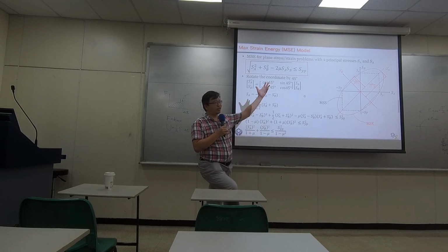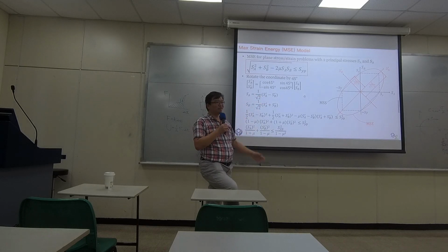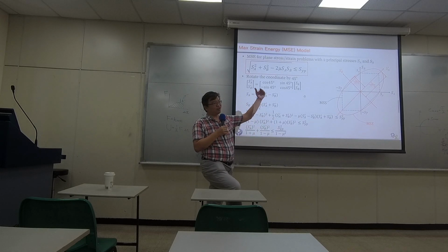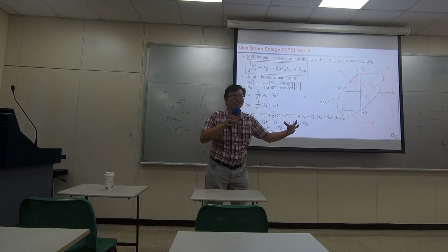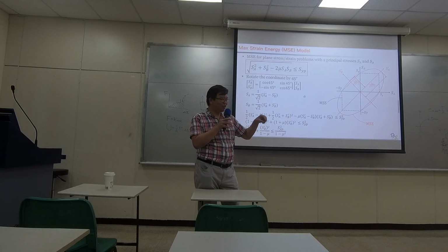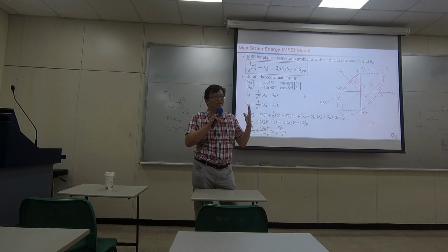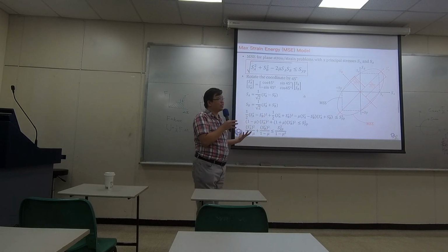If you check the literature and get a value of Young's modulus, it's only an average value of 1,000,000 tests. So the real Young's modulus of a material varies within a range. And even for a piece of metal, the Young's modulus everywhere would be different, because you can hardly have an isotropic material. So how do we deal with it?